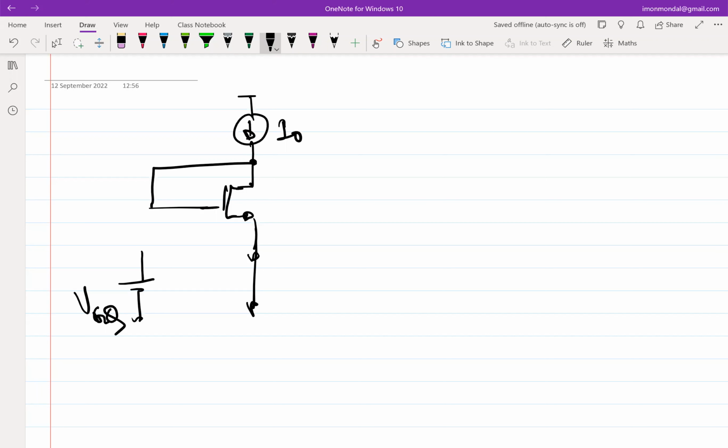It is based on the fact that if I want to bias a circuit with a constant current source, which means I have to add a current source either at the drain or at the source, right? I cannot add it anywhere. So these are the places I can connect my current sources. But how can I change the operation of the MOSFET from the input side?